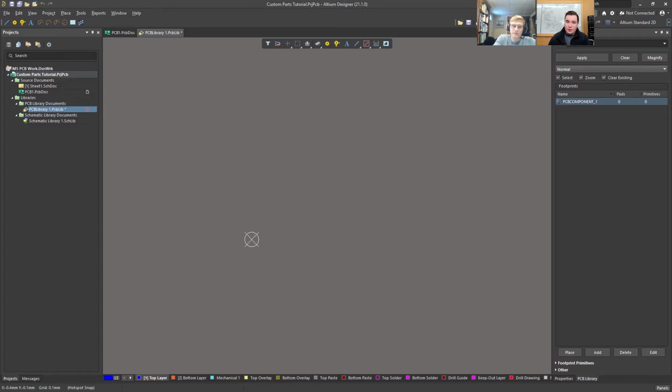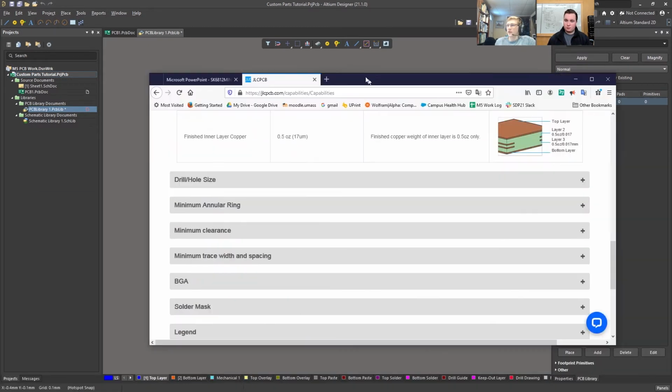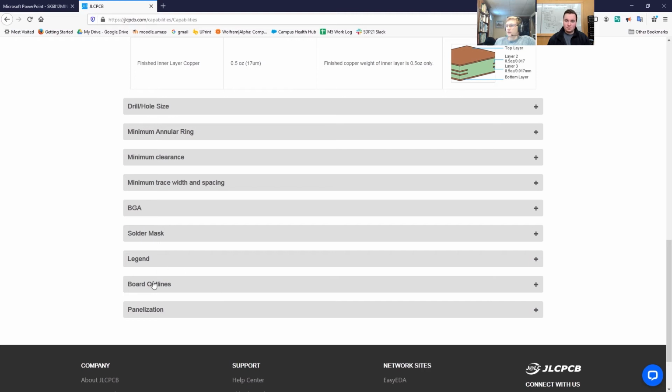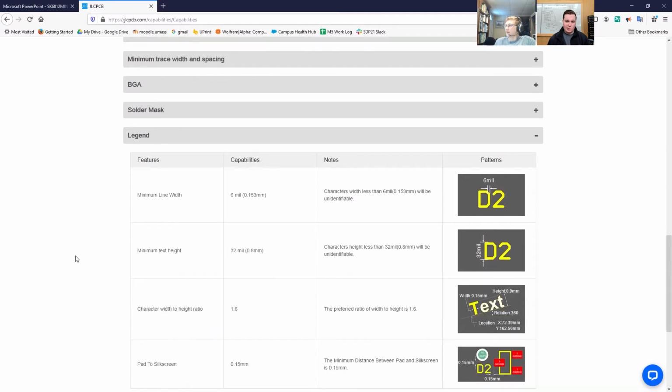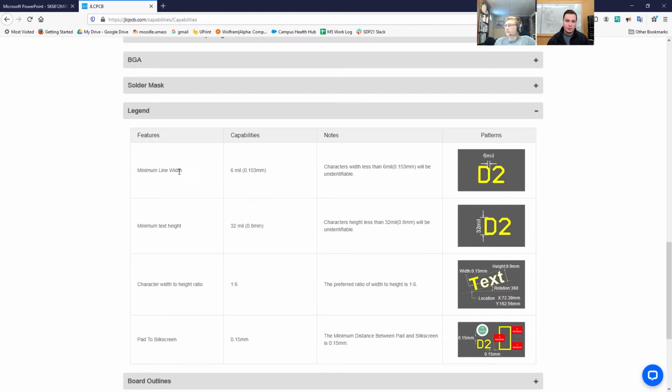They will. Your manufacturer will give you a minimum thickness for your silk screen, and you can go and check that on the website. Shall we do that, Chris? Sure, I've already got it up. Awesome. So where am I looking for here? Yeah, they call it Legend. That'll vary from manufacturer to manufacturer.